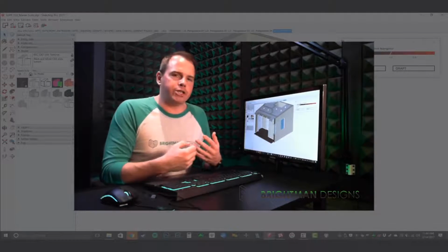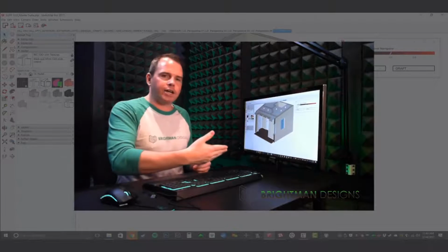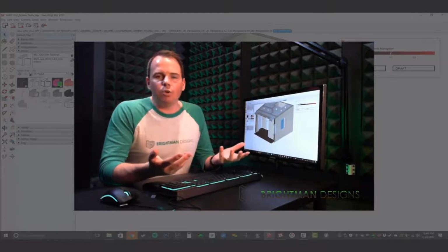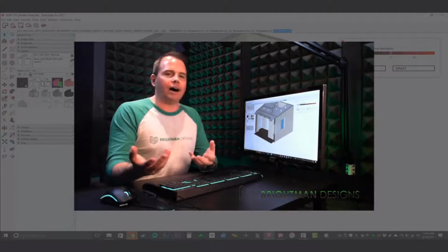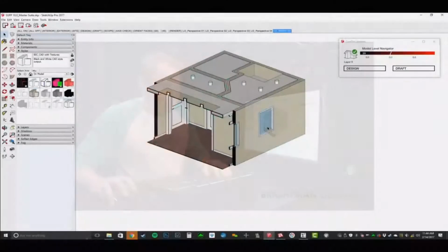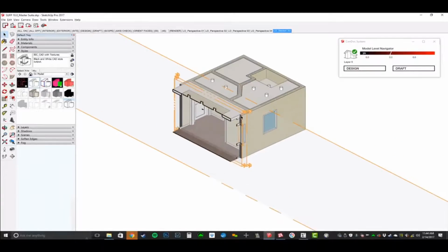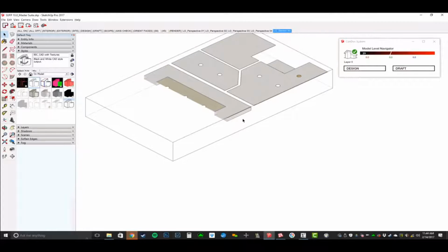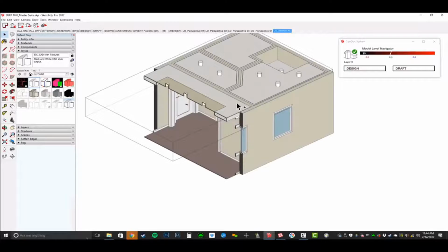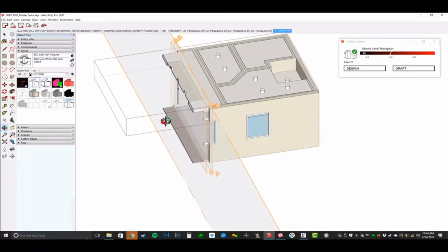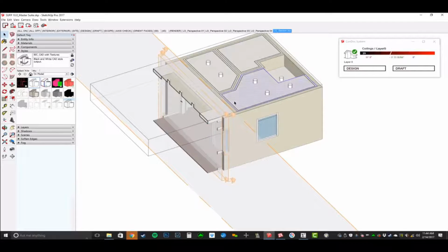on much simpler geometry. If you just chop one section and say add section cut face, it's too hard to know what is a solid, what is not, what should be colored in, what should not be. So at least this way, let's add a section cut face for our ceilings. F6 is my visibility. So I actually don't have one in my ceilings. So let's add a section cut.